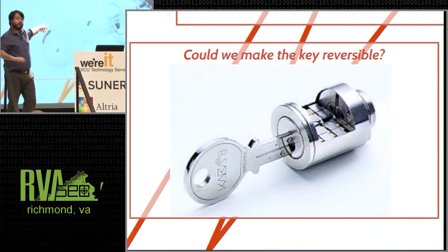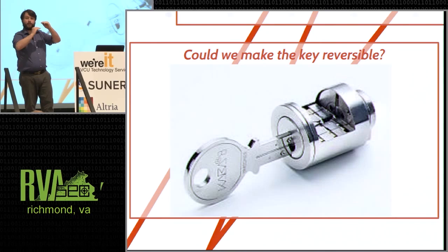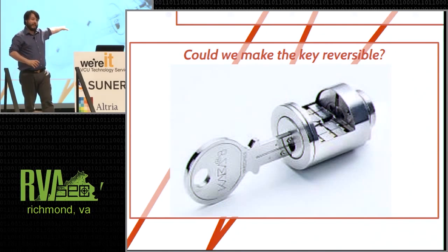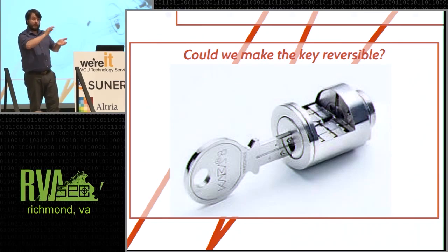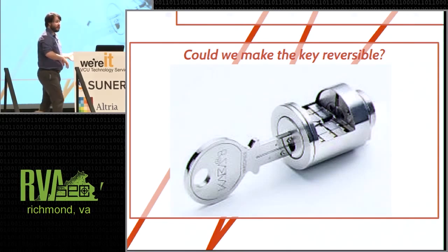When you're cutting into the blade, into the flat of the key, the possible distance traveled is very, very small. So the maximum difference in height between the different pins is very shallow. Therefore, these can be what we call raked. They can be raked to death. We go in with a little corrugated piece of metal, and we just rapidly scrub through them, and because the height differences are so minute, they pop open fairly easily to this specific attack.